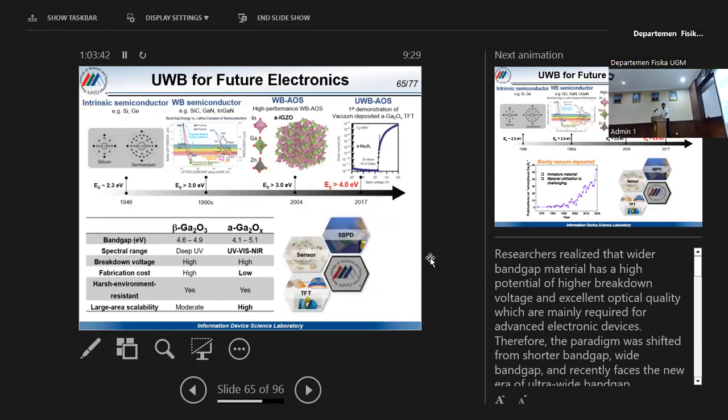But we didn't introduce etching gases like CF4. If you introduce CF4 gas and not only argon, the high energy ions from the CF4 will also interact with your material and it will sputter or etch.